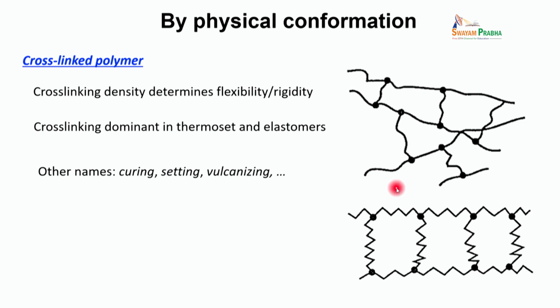So, here I have given an example where we have two polymer chains, and they are cross-linked through a cross-linking agent. Here we have a flexible network and there are a few cross-linking points. This is a cross-linking point, this one is a cross-linking point. So, typically you will see this in a vulcanized rubber, okay. And this is an example of cross-linked polyethylene, right.